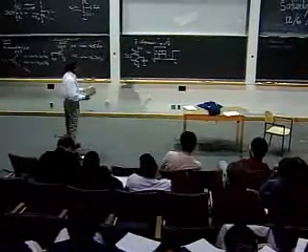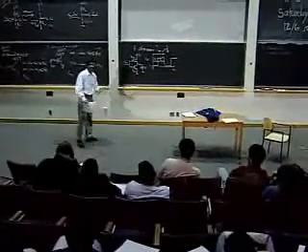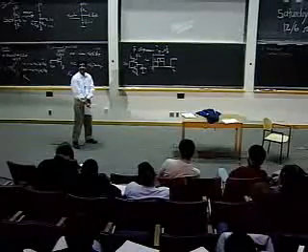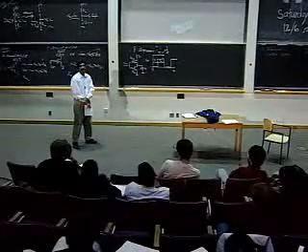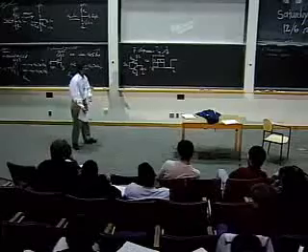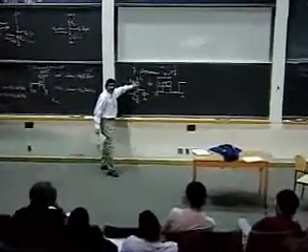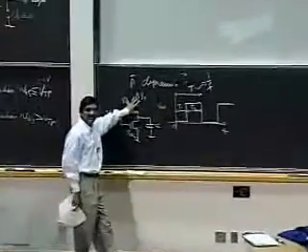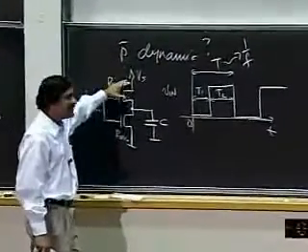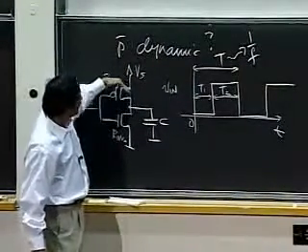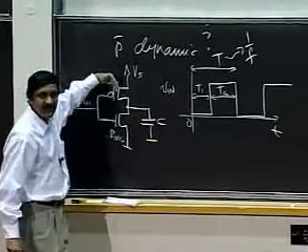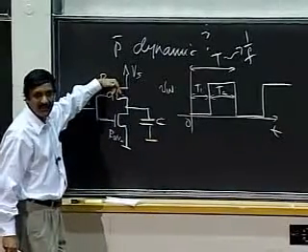What does your intuition tell you? Is CMOS going to be faster or slower than NMOS? Why? That's right. The key here is that the NMOS design I showed you earlier was relatively slow because it took me a while to charge up the load capacitor from the load RL.